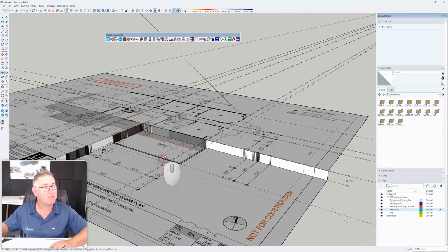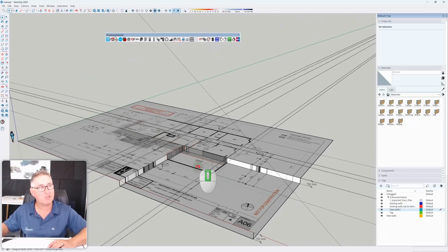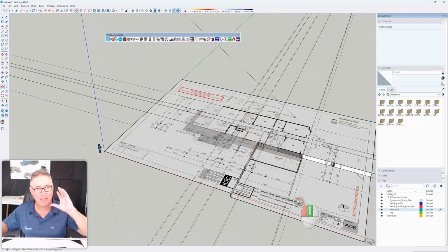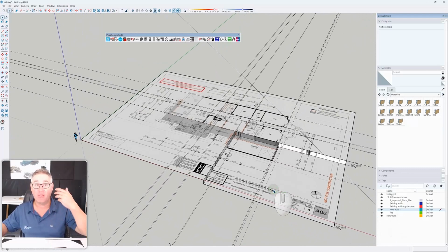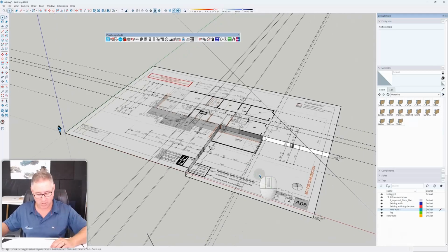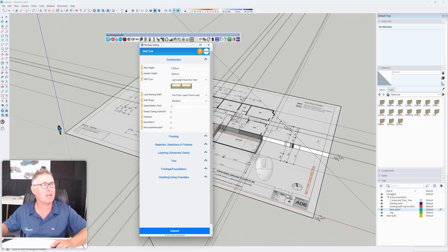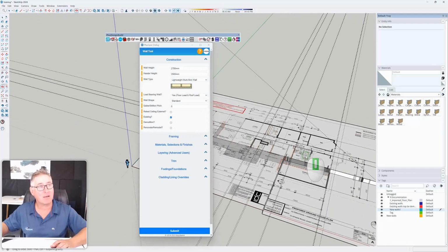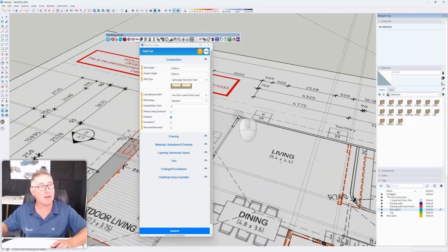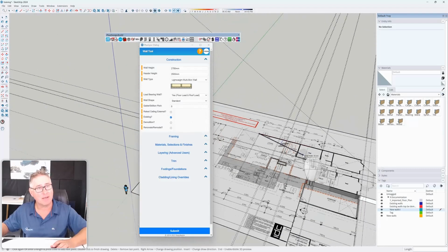The key is to remember that once you're getting too much information and too much clutter, it's starting to get confusion. Then this is the best method to change the color, to use color to be able to figure out the type of wall. And when I talk about type of wall, I'm going to go to my wall tool. I use W as a keyboard shortcut. Is it an existing wall? If it's existing, then go and draw it as existing on top of our black or blue or whatever color I made it.